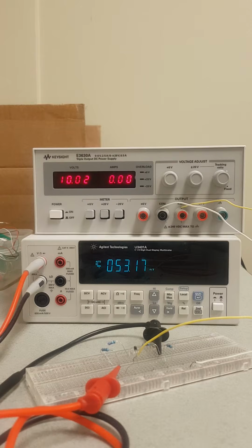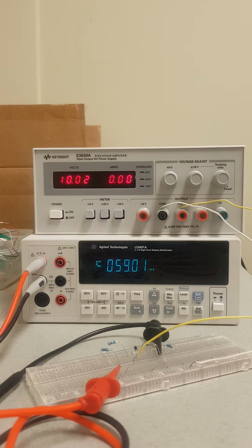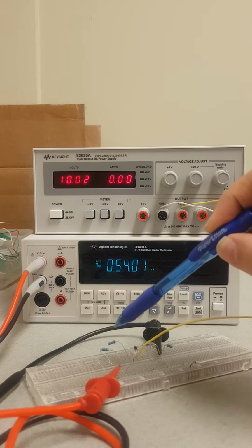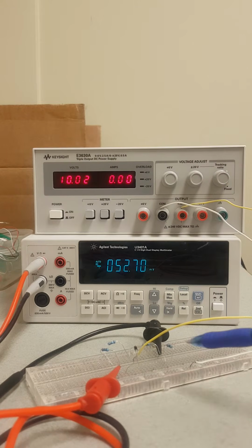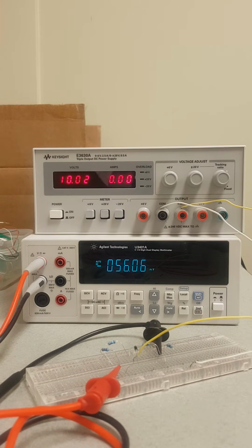Now our thermistor, as we know, is around 11 kilo ohm plus minus. So what I did, I connected 2 resistors in series, 1 kilo ohm. So this leg is approximately 11, and the other leg is 10 and 10 kilo ohm. And when you look here at the voltage, it fluctuates around 39 millivolt, which is a relatively small voltage, especially since we know that for the thermistor, the change in the resistance is high.